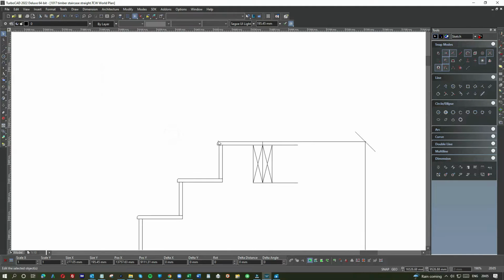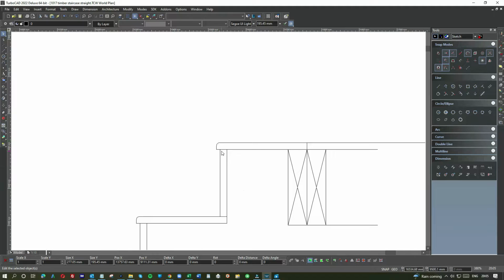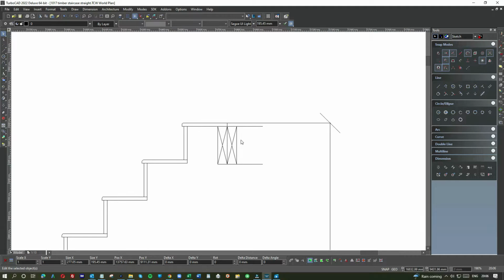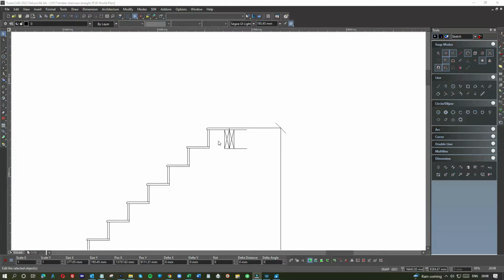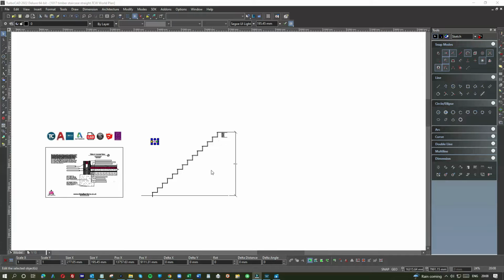So now what we're going to do is fix here. Now normally this riser sits on top of these timbers. So the joists are running that way, and then these timbers are put here. These are called trimmers, by the way. I had a mental block there for a few seconds, trying to figure out what they were called.